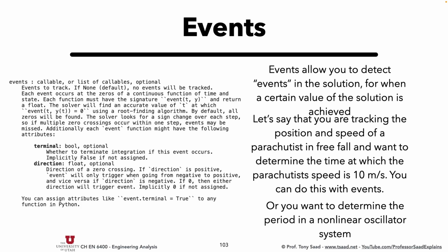So you could say, okay, I'm going to run the integrator for 500 minutes. That's a long time. Okay, the integrator is going to go, hit the ground, and keep going. But if you say, once you hit the ground, stop, it will stop the integrator, even if your t event is smaller than t final, it will stop. Terminal true, stop. Terminal false, keep going. What if there's another event I want to detect? Okay, then I would put terminal as false.